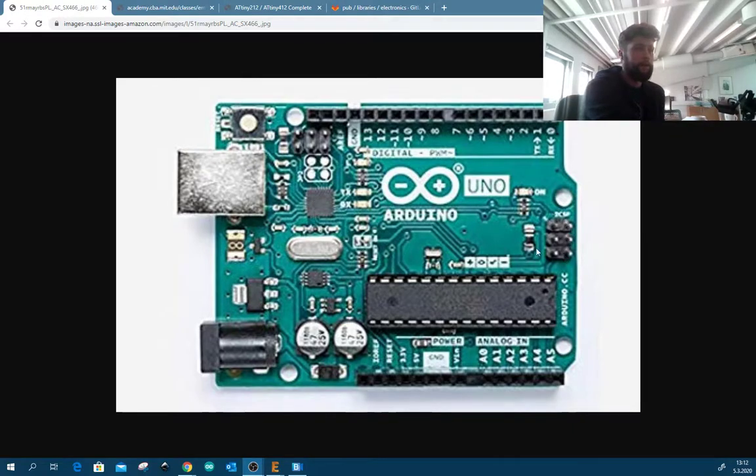And then these pin headers are used to program the initial stages of the brains, and that is the ISP that we made a couple of weeks ago. So you can actually use the Fab ISP to program the Arduino, but you can also use the so-called FTDI interface, or UPDI.